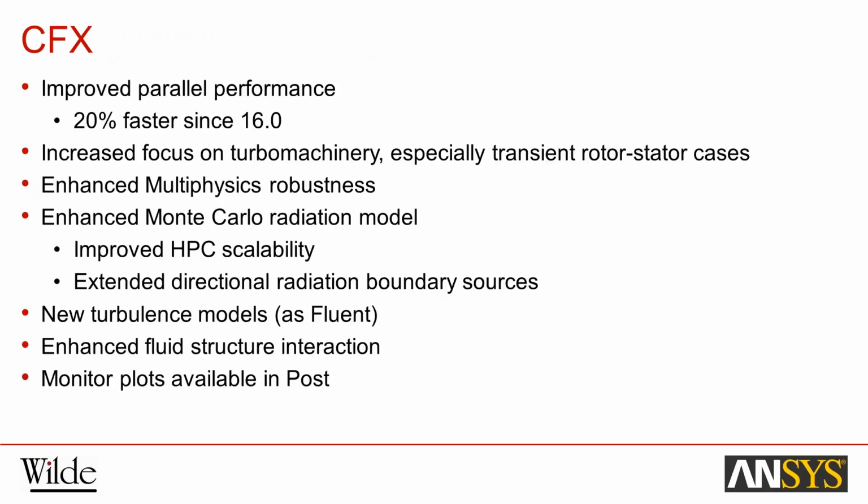CFX. As with FLUENT, there's improved parallel performance. The quoted figure is 20% faster since version 16. There is an increased focus on turbo machinery, especially transient rotor-stator cases. Enhanced multi-physics robustness. Enhanced multi-color radiation model, including improved scalability with high performance computing and extended boundary conditions. New turbulence models, as in FLUENT, as in the previous slide.